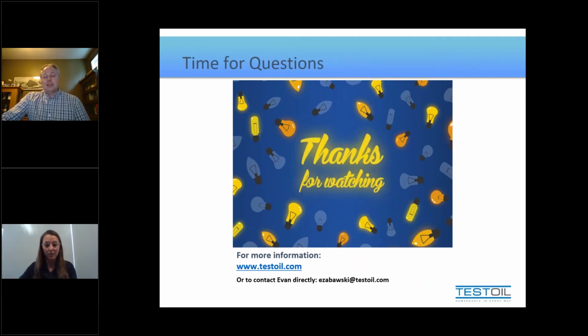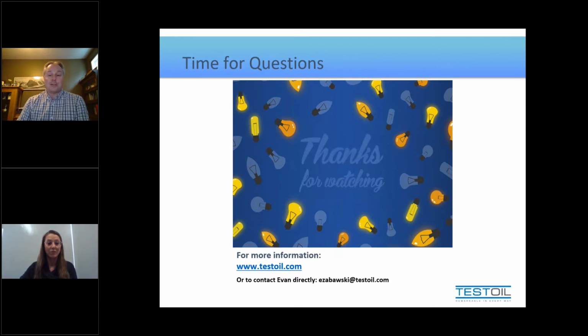The biggest difference is that the way NAS is done is what we call differential. The ranges are defined 5 to 15 microns, 15 to 25, and so on and so forth. Whereas ISO is what you call a cumulative count, and it is 4 and up, 6 and up, 14 and up. So they don't cross compare, but they're of the same type. They're, like I said, the cleanliness goal. But no, they've got nothing to do with filter ratings from that perspective, if that's what the question was asking. I hope I understood it correctly. It sounds like you did. I believe you did answer the question there.